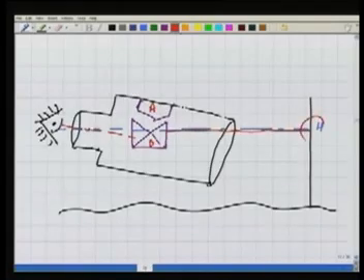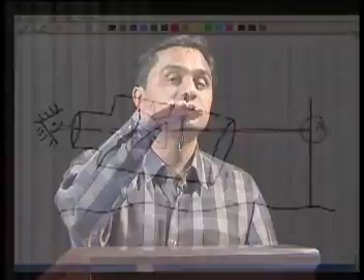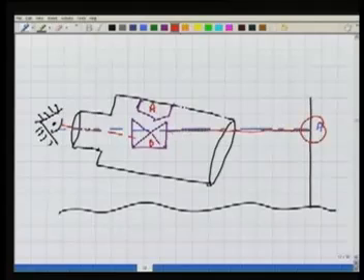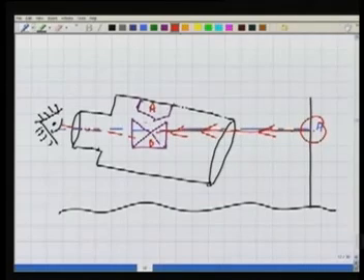So the point H, which is being intersected by the horizontal line of sight here, the rays travel over here, and again by the optical assembly B and A, they get reflected in such a way that what my eyes see now is still point H. So even if my telescope is slightly tilted, I am still looking at the same point H.